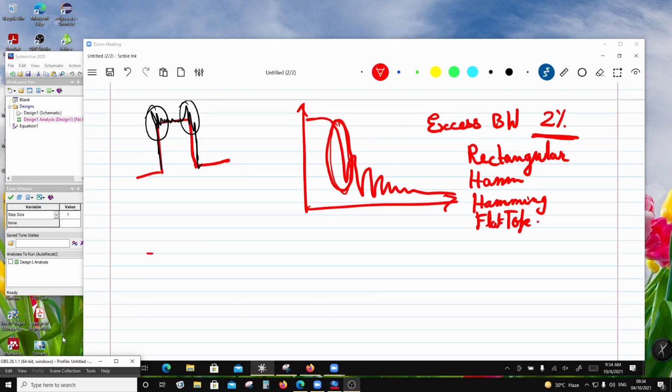Now if low pass filtering is done, then when you transmit it, these edges are going to become fine, not so sharp. So this is low pass filter. Now if I want to enhance the higher frequencies, I can do some form of a pulse equalization. So this pulse equalization also becomes important.